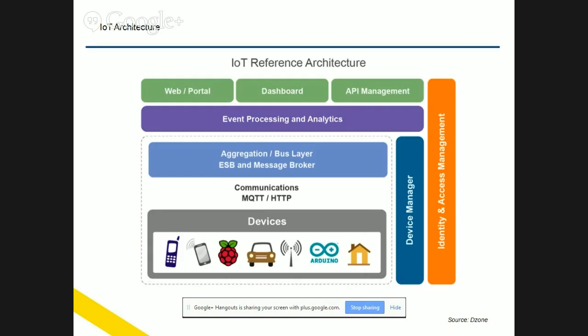The next thing is we would want to run analytics on the data that we have collected. So, for example, we would want to know what has been the trend of energy consumption in the house. So we get an idea of how energy is being utilized in the house. This will give us an idea of what action we need to take to optimize use of electricity. So that's done using analytics.